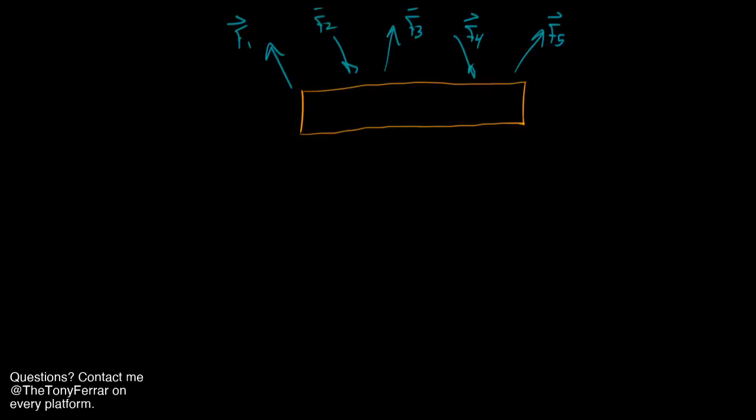This might feel a little weird on rigid bodies because the forces are spread out and you know intuitively there's more going on here, so it should feel a little weird. The moments caused by each of the individual forces have to be accounted for too, and we'll do that by finding the moment caused by each individual force and then finding a resultant moment, but that is the topic for another discussion. For now, what you need to know is we can add up all of the applied forces on a system and replace them with a single resultant applied force that has the exact same effect.